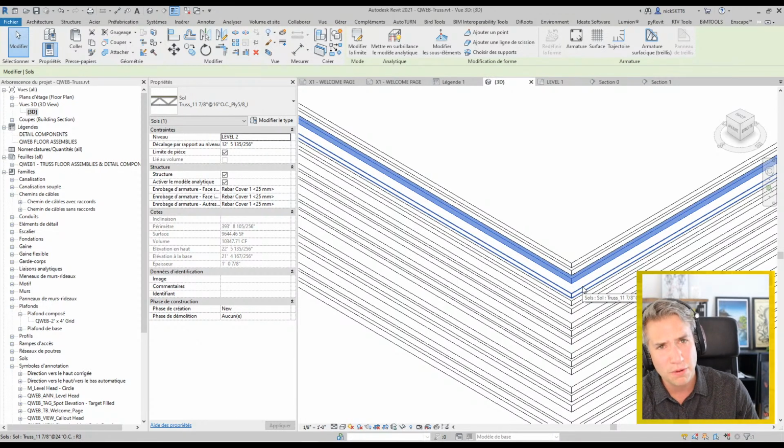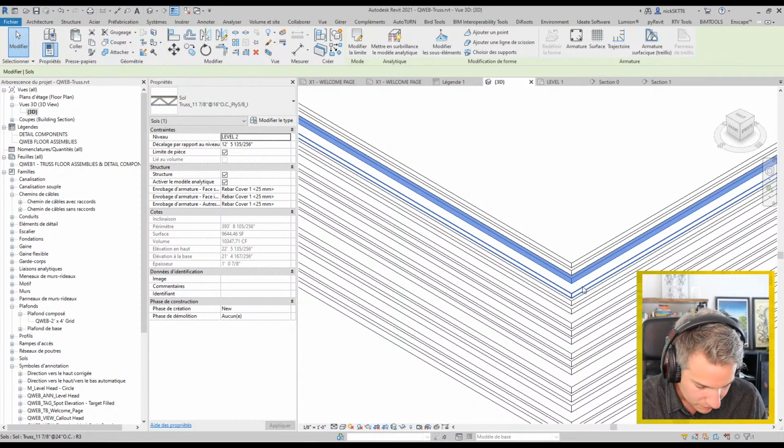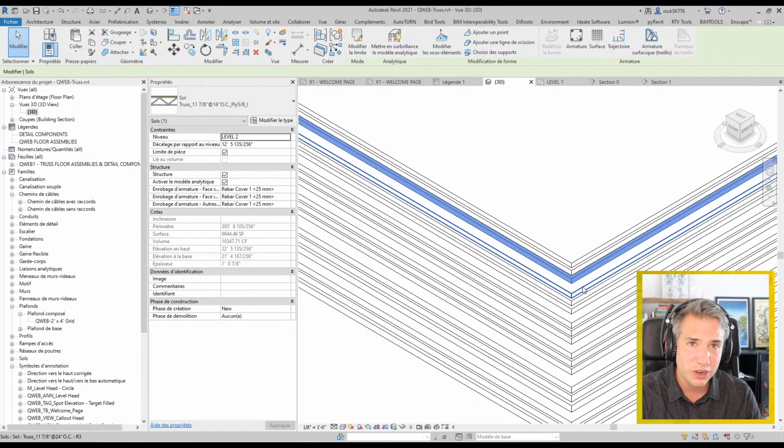I would say this is made for preliminary design. If you're getting started and you want to quickly create a section, it's a great way to do it and have the matching depth of the floor. Eventually you can switch to having real truss families, 3D families. But you know, in some projects like houses, for example, maybe modeling all of the truss will be overblown, right?